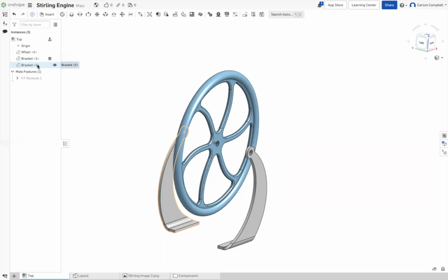Why is that significant? So say I had a bolt, so let's say that I had 100 bolts. What would happen to a part studio? It would come crashing to a halt. Yeah. What if I had 100 bolts inside of an assembly? I don't care. Oh, you want 1,000 bolts? Okay. Why? Assemblies give you two things: motion, and they give you instancing.